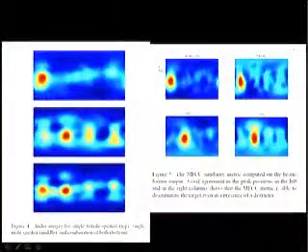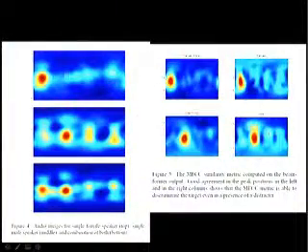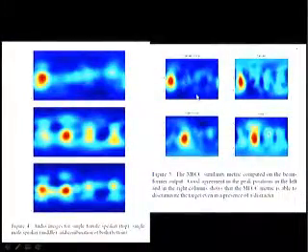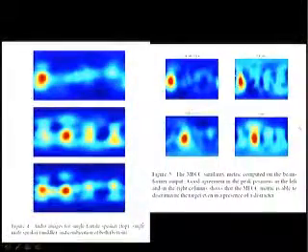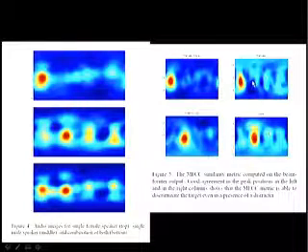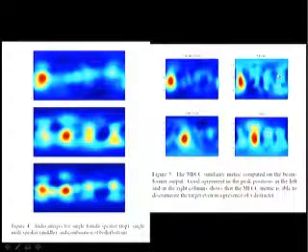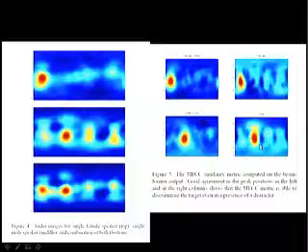And here, we now run this MFCC similarity metric for every direction, and it tells us this location, this location, and this location are the locations of the reflections for the female. This was run first on the case where we had the female alone, and now we ran it also on the case where we had both the female and male speakers, and we are still able to locate the reflections which correspond to the female. Likewise, we did it for the male alone and for the male in the presence of the female, and again we are able to locate the reflections which correspond to the male speaker.